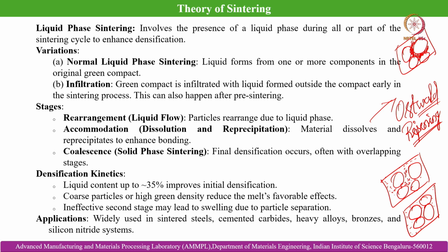So, when a pre-sintering is done with the objective to achieve some amount of density increase compared to the green density, and also when the porous network is fully evolved because the binder ingredients have totally left the powder compact, then there is enough porous architecture within the body undergoing sintering, where the liquid can be infiltrated, and then it can proceed with the liquid phase sintering further.